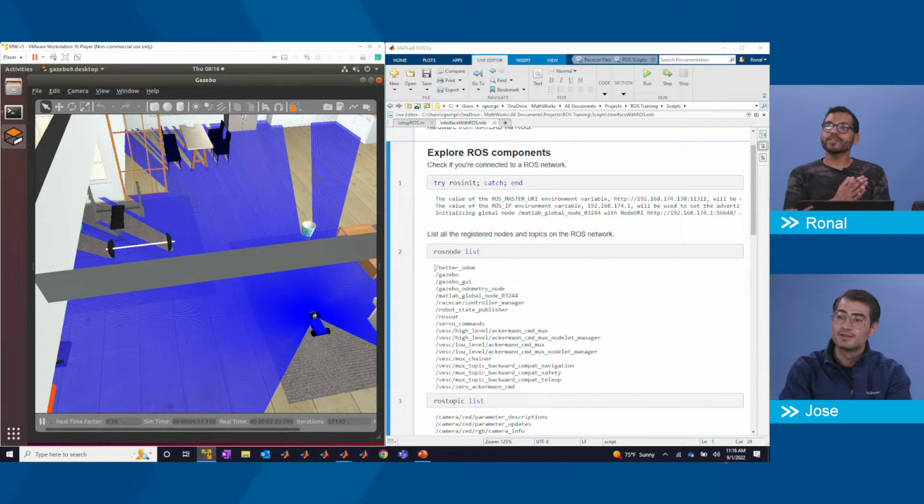Yeah, so this robot actually comes with a package that lets you have different levels of control over it. Say you have an actual RC controller in your hand, plus you have an autonomous script, and maybe sometimes you want to take over. Maybe the autonomous script is navigating in a way you don't want to go, so you can have a prioritized RC controller that can override autonomous commands. So that's available there. There's an individual node for the camera, an individual node for the LiDAR, and an individual node for the actual actuation. That's why we have most of these.